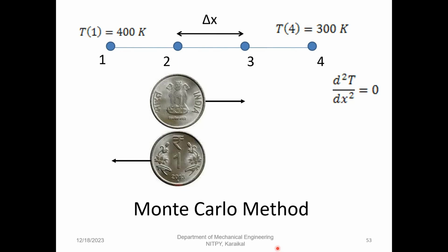Now when you go with Fluent, we'll be dividing the domain into multiple segments. If you have a very large domain, the system will divide it into 8 parts, and each part will be given to one core. From the inlet to the first segment, it will be solving, and then that result will be given to the next core. So when you go with more points and more divisions, the time taken for information to pass from one core to another becomes higher, and the total time will increase.